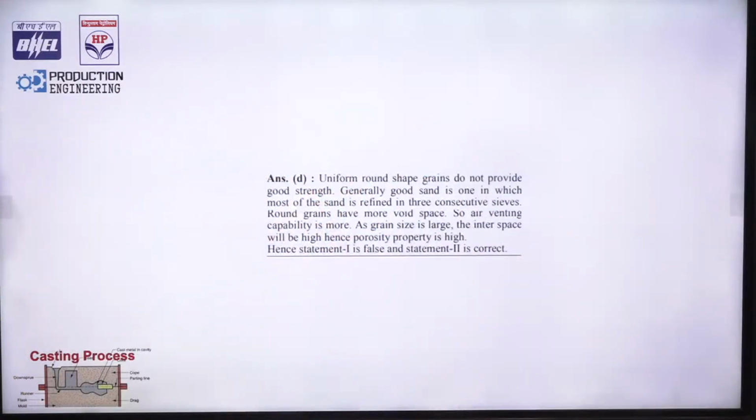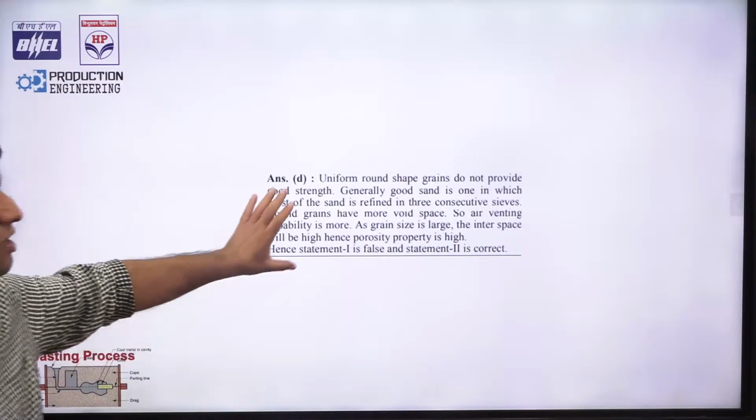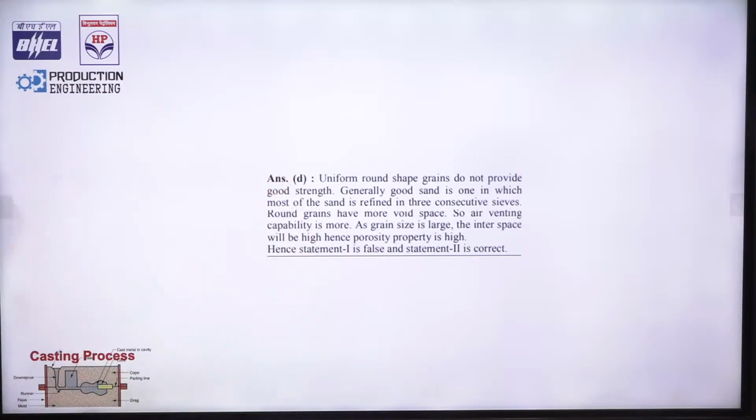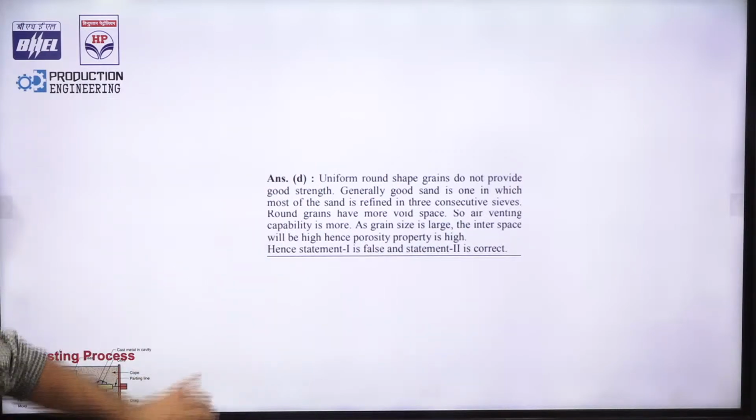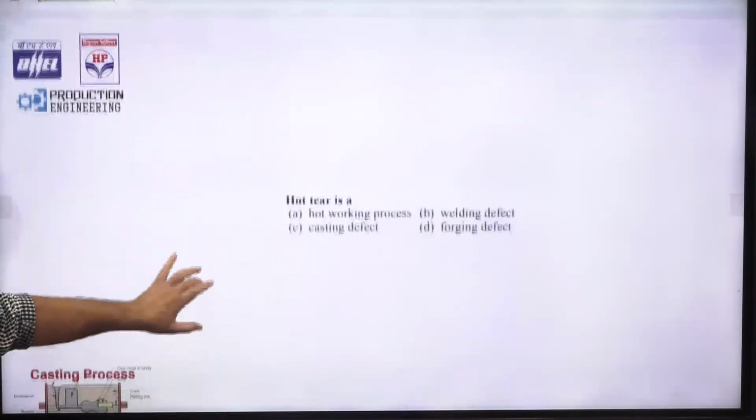Sand is basically in different shapes and sizes. If the grain size is high, then the porosity property will be high. Porosity is high if the size is more. So grain size is also one of the very important parameters in deciding the properties of the sand.